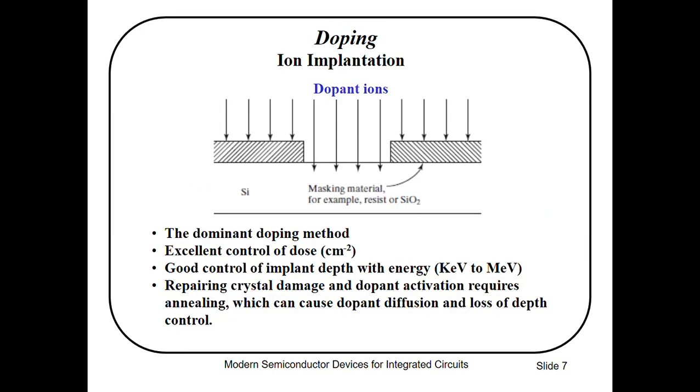Doping. The density profile of dopant atoms in the silicon is generally determined in two steps. First, the dopant atoms are placed on or near the surface of the wafer by ion implantation, gas source doping, or solid source diffusion.